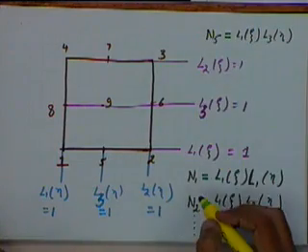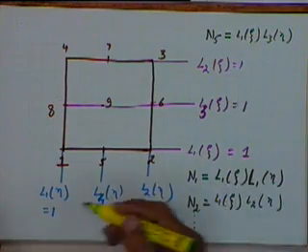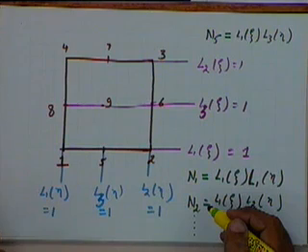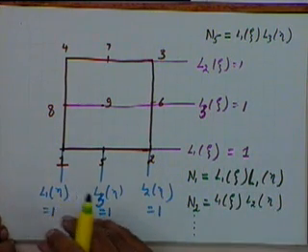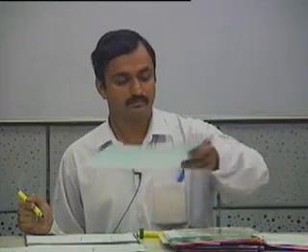Okay, and again once I define the shape functions, the process of finding out the stiffness matrix and the force matrices remains the same. So in any element, the basic thing is to specify the shape functions for the element and define the element accordingly. The stiffness matrices, force matrices, etc. can be found out by a process of integration, which we have already seen a number of times. Is that okay?